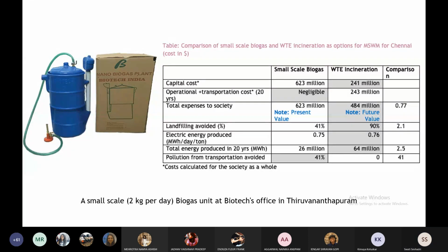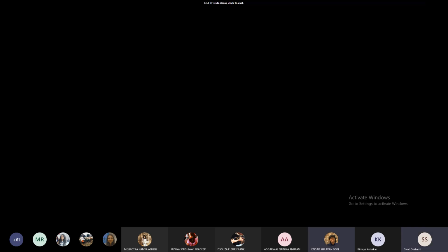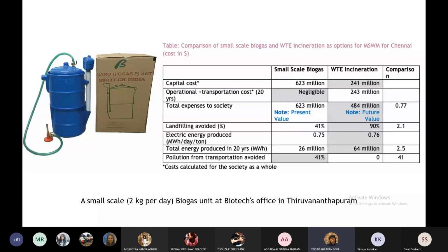Okay. I should probably look into a bioreactor instead of using the water. Instead of using the water, I can take it into a bioreactor. Is that what you're saying, right? Exactly. Now, you need to also understand this is the capacity, around 2 kgs per day. If you want to design a biogas digester, you should put one of these into your system. On the right hand side, it has a vent pipe, and from the top it takes the gas. The whole masonry big ones that we saw earlier, this is just a packed, smaller version of it. Fair enough? Yeah, I'll look into something like this because I do have a kitchen on site. So, we are done with this one.